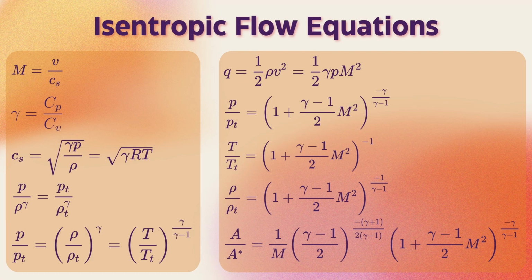Here, the isentropic flow equations that the modules use to solve everything in the nozzle revolve around this gamma, which is in the second equation, the ratio between the specific heat capacities of the exhaust at constant pressure and constant volume. You can find all these different ratios, which allows you to ultimately solve for the mass flow rate and the exhaust velocity.